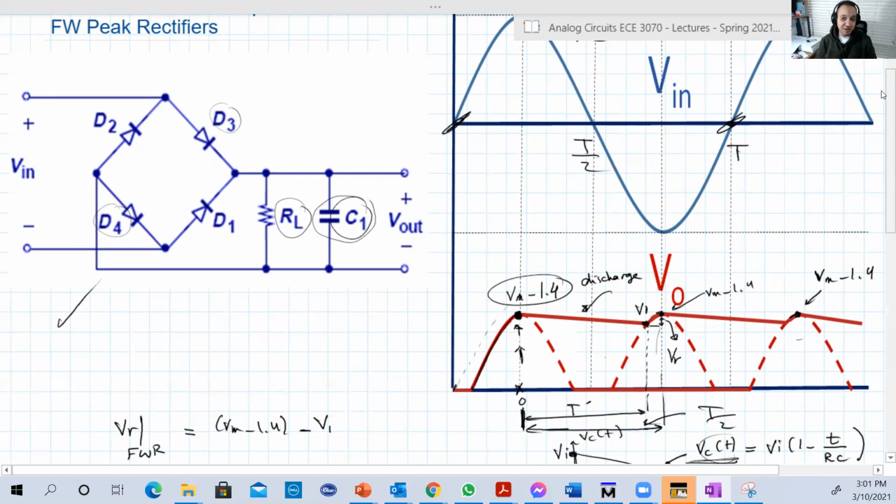Our next lecture will be basically the last lecture in diodes, in which we're going to study the Zener diode and also its application in such full wave rectifiers to get perfect DCs. When we make this modification and add the Zener diode, we will get what's called a voltage regulator or DC regulator. This Zener will act as a DC regulator. It will regulate our variation to just constant voltage. It will change this small variation, this small ripple, into a perfect constant